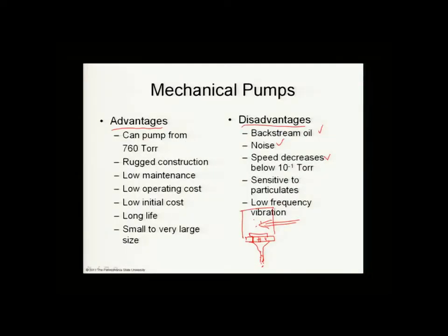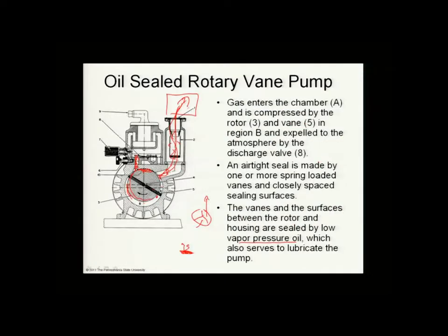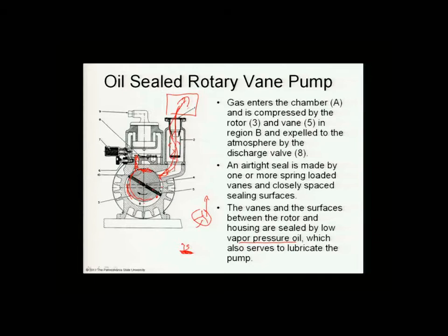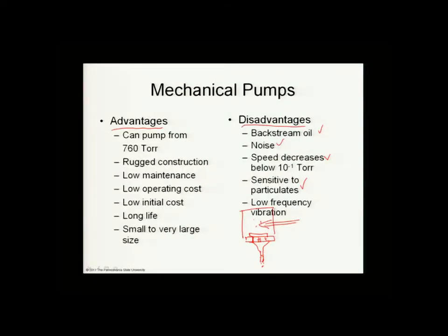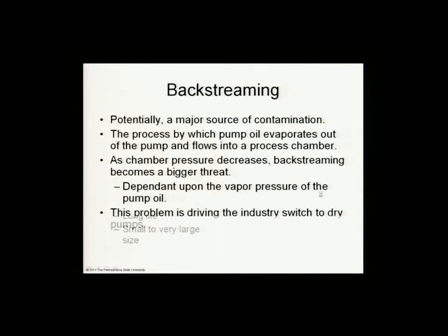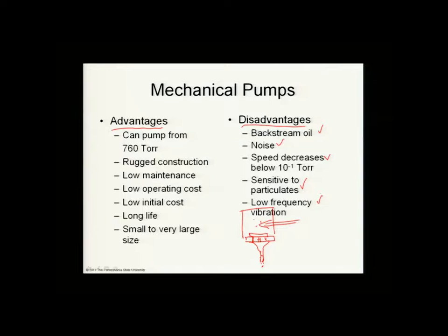And they can be sensitive to particulates. You can see why that can be the case, because things can get ground up in here. They really hurt the pump. So if you have some process that's producing some particulates, then you have to be very careful here. And they generally have low frequency vibration, which is good. The low frequency vibration is a good attribute, so that belongs over in the advantages category.